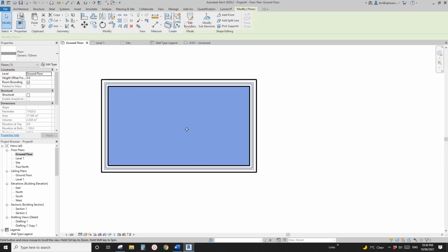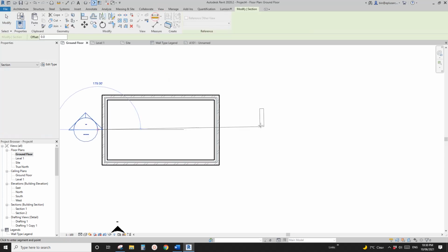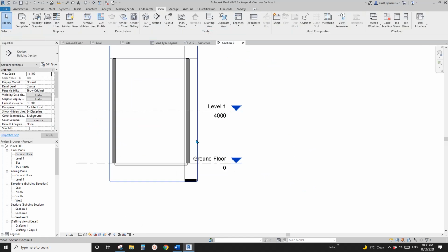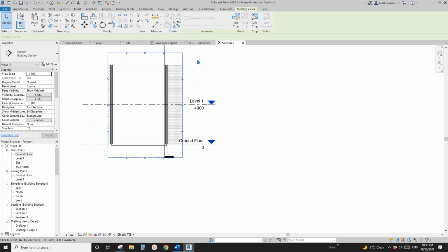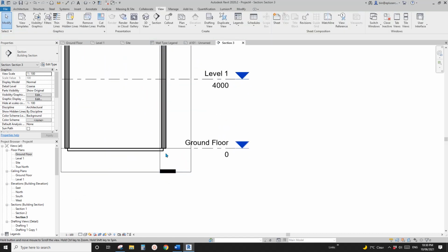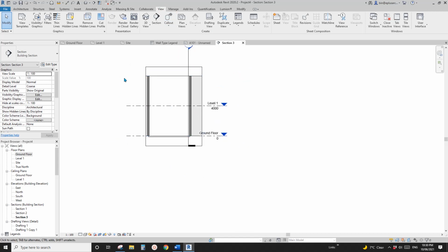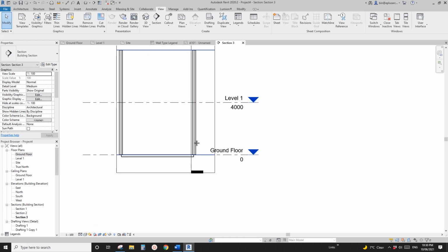So finish it, and then I'll just do a section view of this. Okay, and then go to the section view. From this section you can do another callout. Sometimes you will have all your sections drawn up, and then you change the detail, and then you can just do a callout.